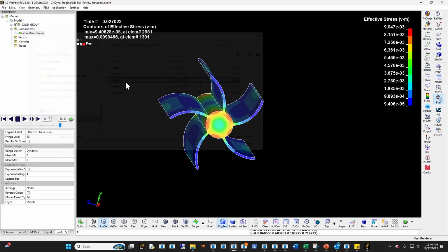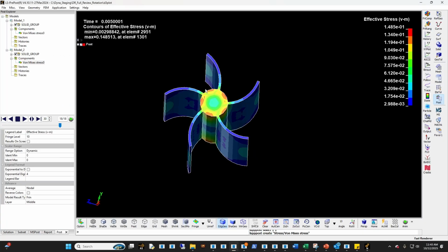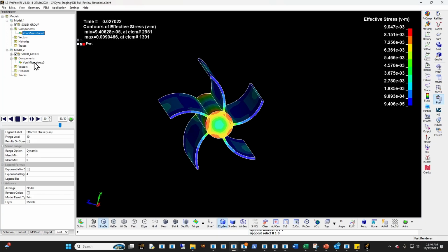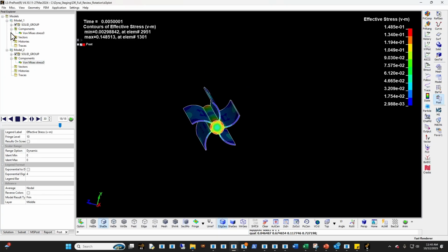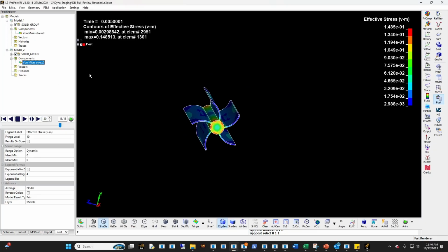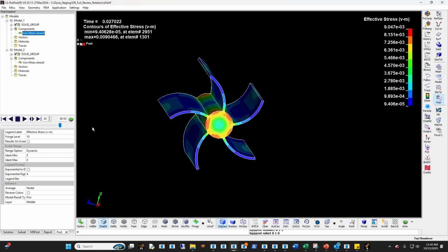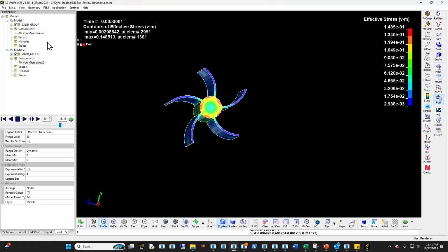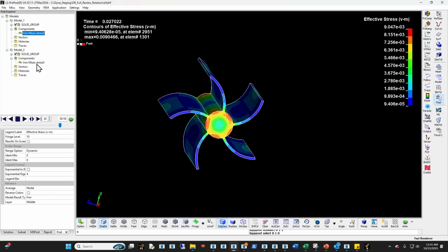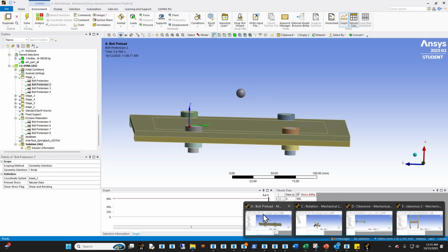And then if I take it to the full transient, you get a similar situation to the previous example. I didn't have any additional load, so you get basically the same stress, relatively speaking, across. This one just damps out the system, and this one gives you the full stress as a function of the transient analysis. This one right here just initializes the stress and makes sure the ringing in the system is 0, and this one you have the full stress that you can actually look at. Okay.